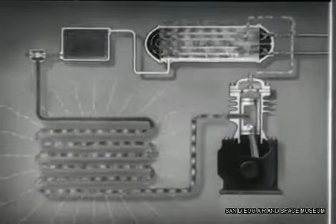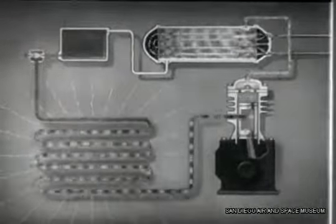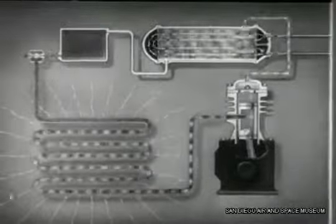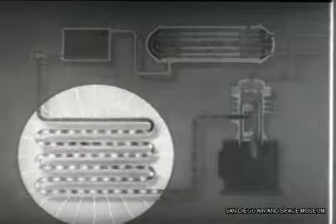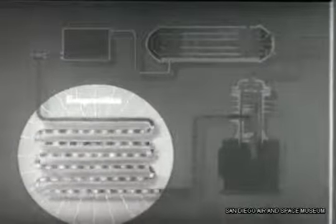This is the refrigeration cycle. How about watching it again, quickly? The high-pressure liquid refrigerant flows into the thermal expansion valve. It breaks up into small particles and expands into a larger space, becoming a low-pressure liquid. It then goes into the evaporator, where it evaporates and absorbs heat. It is now a gas, still at low pressure.